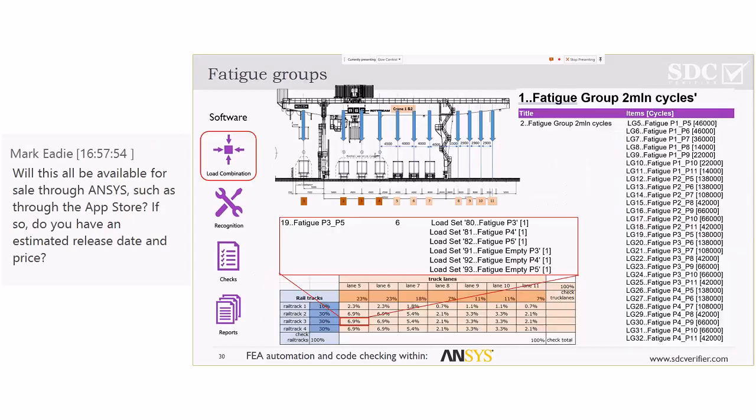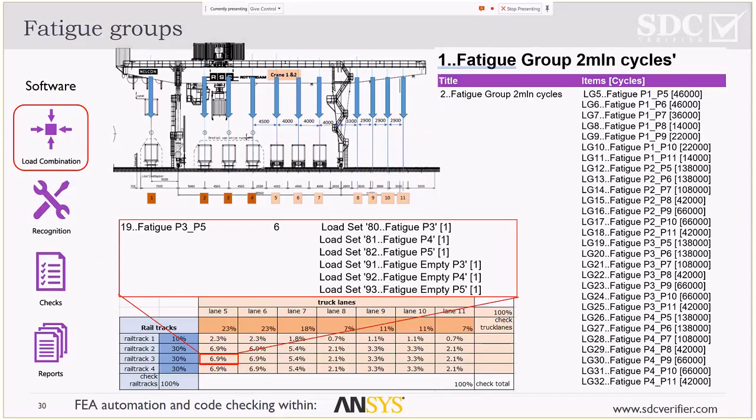We show you also how to use different groups. In general, you need a couple of groups to do static checks according to still water conditions or survival conditions, but you can also use the same method in fatigue groups, because you can set different movements, for example from here to there, or from 1 to 5, or from 3 to 5, or from 2 to 7.